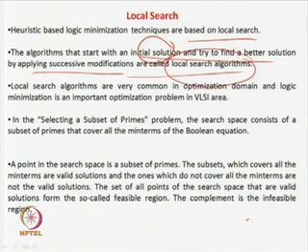After doing this modification, your function should remain equivalent, and then you should compare whether the number of literals and the number of product terms are decreasing from the initial solution. If so, you keep it and then try further modification. This is called local search. Local search algorithms are very common in the optimization domain and minimization also in the VLSI area. So, what does local search mean?